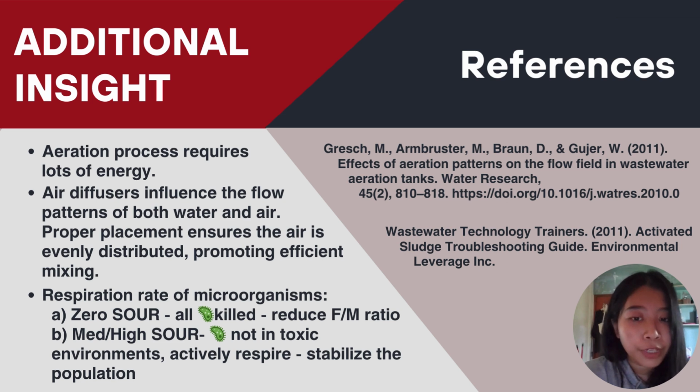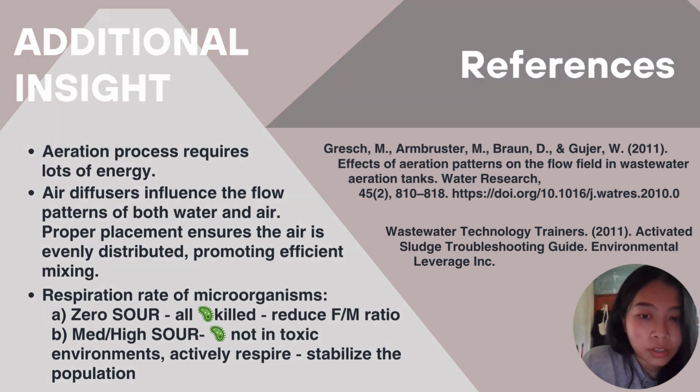This usually can be fixed by reducing the feed to microorganism ratio, feed referring to the organic matter while microorganism referring to the aerobic microorganism in the wastewater. When the SOUR value is medium or high, it means that the microorganisms are not in toxic environments, and they actively respire. So the best step to take for this case is to stabilize the population to ensure an efficient degradation of the pollutants.